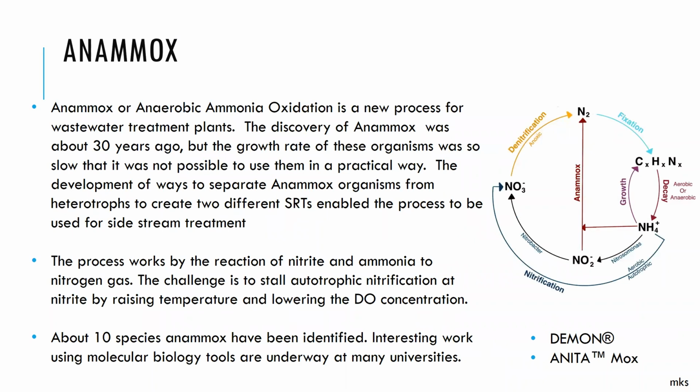And so there's another process that's become popular, and it's Anammox. And Anammox is sort of newly discovered, newly being 30 years or so, which goes a sort of short circuit across the nitrogen cycle. And you can combine nitrogen in the form of ammonia and nitrite in sort of anaerobic conditions to make nitrogen gas. And so it's not the easiest process to operate, although we're learning how to do it better and better.